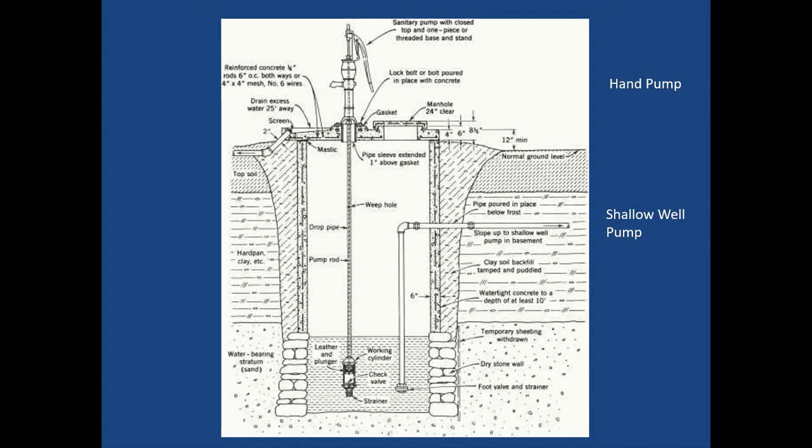You would need to have an in-well pump, submersible pump, if you had a deep water well, because water is more easily pushed than pulled. And so that could also have an effect on the types of hand pumps one might use for the well, depending on the depth of the well.